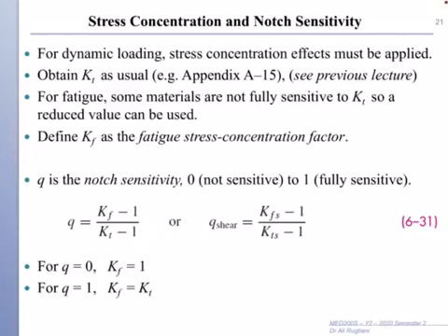Okay, so in dynamic loading, to estimate accurately the strength of failure and fatigue, you need to apply stress concentration effects if there are any.